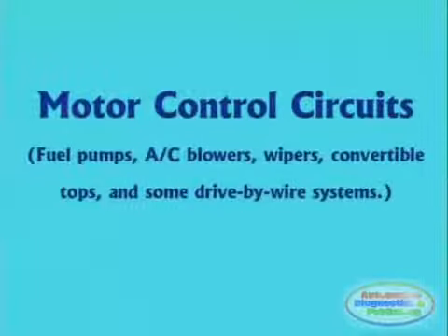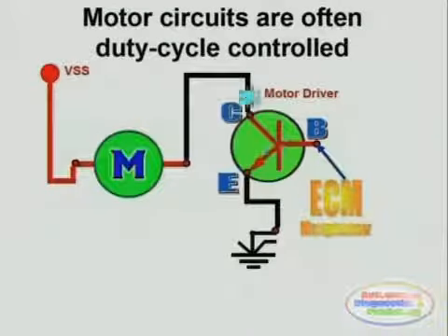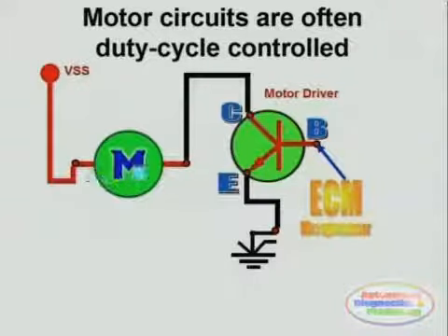Duty cycle control motor circuits are employed in a wide variety of components such as fuel pumps, AC blower motors, wipers, and any system that requires a varying motor operation. In this case, we see how the motor is duty cycle controlled by a driver or transistor.